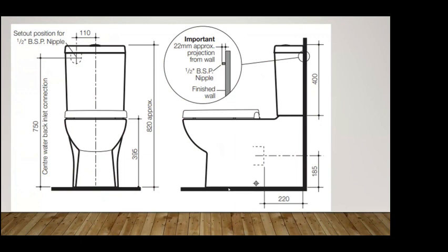Ones you've got to watch out for are wall hung pans, and you've got to watch out also for the finished floor level. They can be quite low anyway where they sit. So you've got to set the bracket up and everything, and you've got to consider the finished floor level. If it's a wooden floor like this and that's going to be the end one, well, that's fine, that's great, that's what it is. But in a hospital, sometimes they build it up 30mm or something across the bathrooms to put a heap of fall on it.